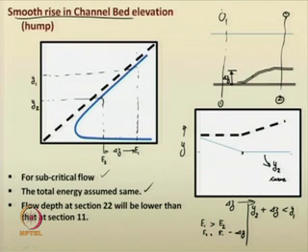That critical depth will be maintained as such. Similarly, the upstream flow depth will remain same, even if you increase the hump height, till the critical level, then the upstream depth slowly increases. This is the depth of flow versus the hump height profile if you observe for subcritical conditions.